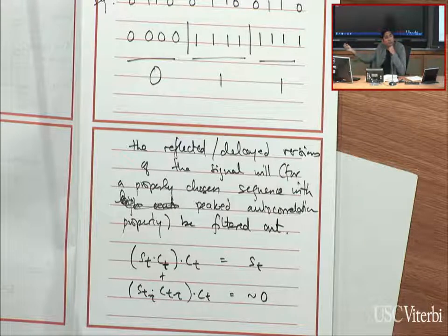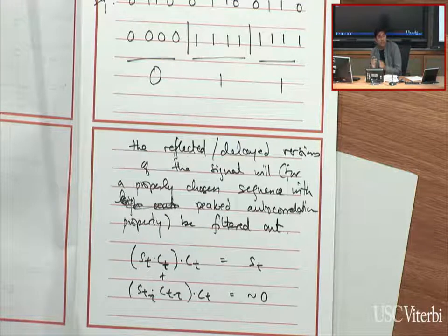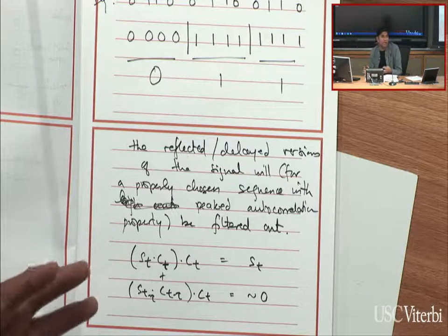They won't show up in the received signal. And so even though they have all of this multipath reflections happening, I'm getting the original symbol plus delayed versions of that symbol. The delayed versions of that symbol don't correlate well with my decoding sequence and essentially get filtered out. Right. So again, this is not the class for us to get very deep into the idea, but the takeaway lesson is that by using carefully designed spread spectrum sequences, these chip sequences, you can essentially filter out delayed versions of the signal and therefore perform really well even in environments with high delay spread.